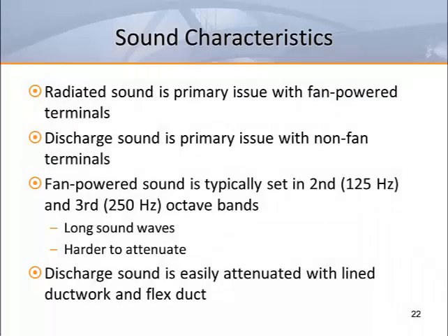When discussing the acoustical performance of fan-powered terminal units, radiated sound is usually the main concern. Fan-powered products typically generate low-frequency noise in the second and third octave bands. This low-frequency noise is difficult to attenuate because the wavelength is long. Unfortunately, this low-frequency noise tends to pass through ceiling tiles. Ceiling tiles do a good job of blocking high-frequency noise, but are acoustically transparent to low-frequency noise.